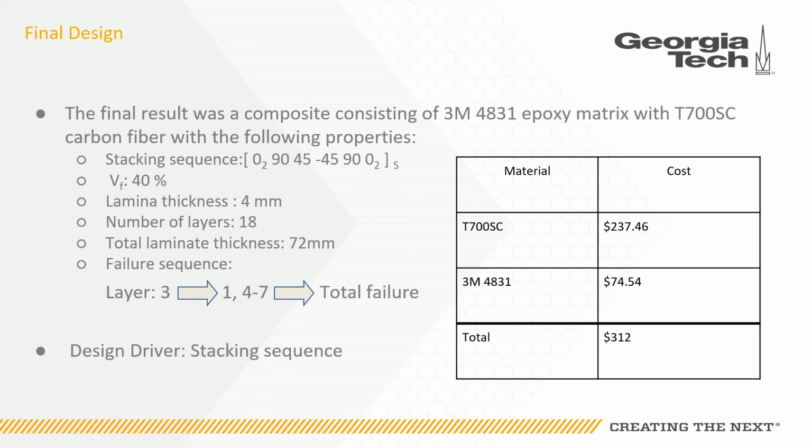In conclusion, it was determined the design driver was the stacking sequence. The cost of $312 seems to be well within the range of aircraft components, and the total laminate thickness of 72 mm meets the criteria of the assumptions in lamination theory that the laminate is both thin and wide.